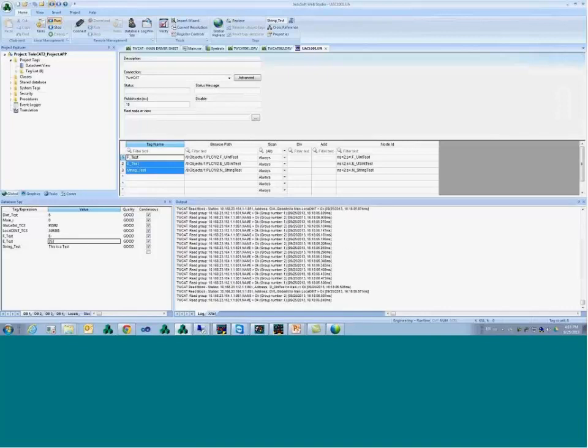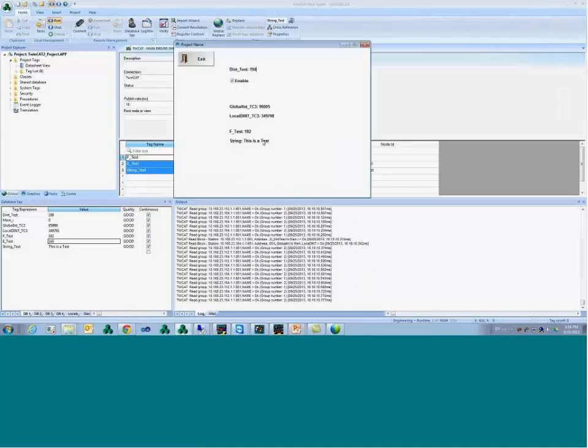Okay, so now I have here my runtime. As you can see, we're talking every 10 milliseconds to the PLC through OPC UA. As you can see, it was very simple to configure that. All you have to do is on your TwinCAT, you install the OPC UA server, you install the license, and when you're configuring the variables,